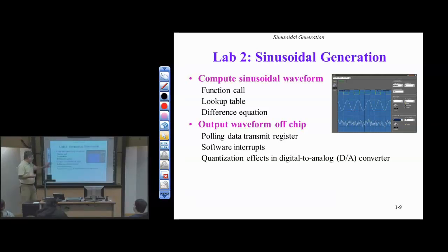The 3rd case, which isn't up here, is to take a block of data and get it off the chip at one time. This is known as direct memory access transfer, which is very commonly used in instrumentation and processors. It takes a block of data and gets it off chip all at one time instead of one sample at a time. And no matter how we get the data off the processor, we're going to do the calculations, and the computation will be done in floating point. So we'll do everything in 32-bit float.